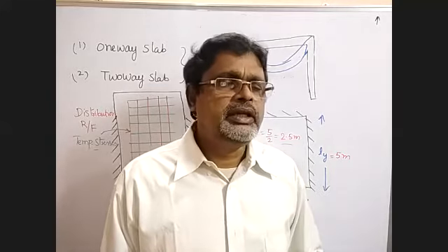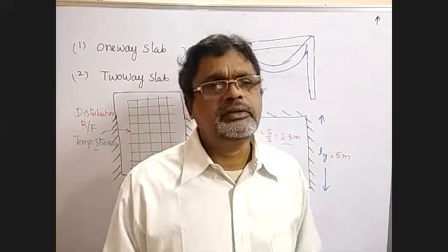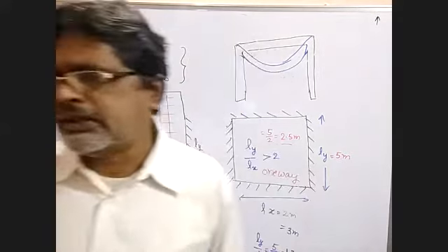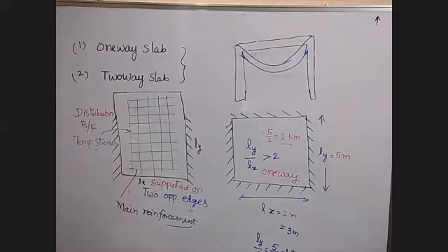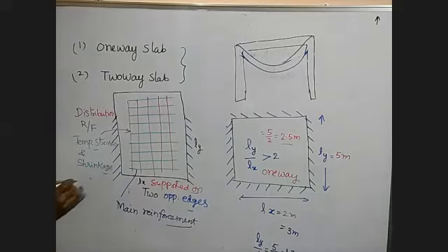So in that case, the steel heats up. Because of that temperature, the temperature stresses will develop in the slab. So to take care of that, they will provide the distribution reinforcement, and also it will take care of the shrinkage, and also deflection. It reduces the deflection also.